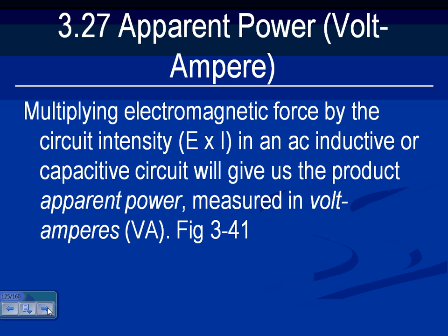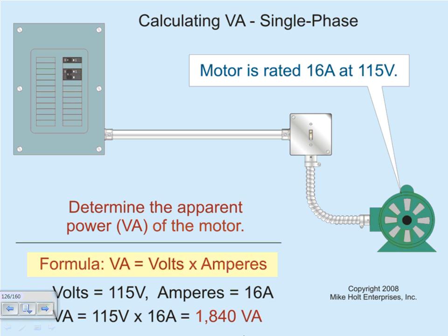That's really my intention of the whole chapter here. Single phase current calculation, determine volt amps. Now, this is where I want to do some calculation later on with you: moving forward, you wouldn't talk to Chad about KWs when we talk about equipment. We always talk volt amp. Don't talk KWs. KW is meaningless unless you give me the power factor. So from now on, you're going to be talking about volt amps.